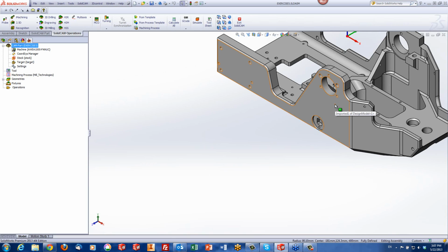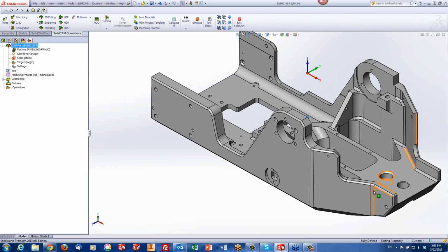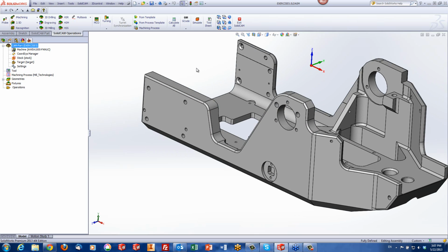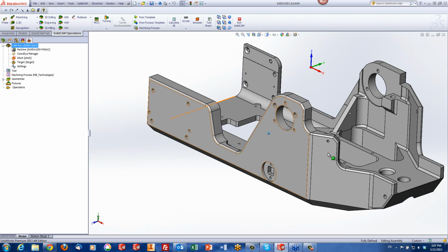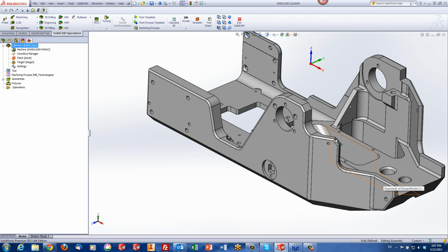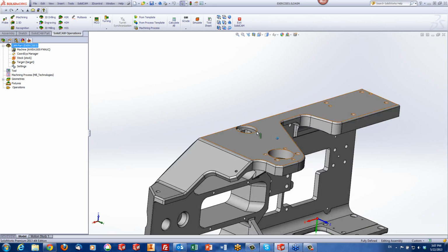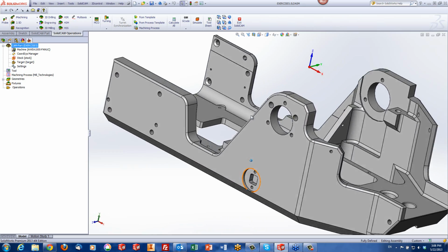In this part we have over here, this is a typical case that many people sometimes run across, where they have a fillet as shown over here on this edge. Now, people would think to themselves, maybe, I'd like to work with a concave type of radius tool, but that's not really going to work over here. One, because you can't really do it this way, going up and down like that. Even if I had it lying on its side, I would still have the problem over here.